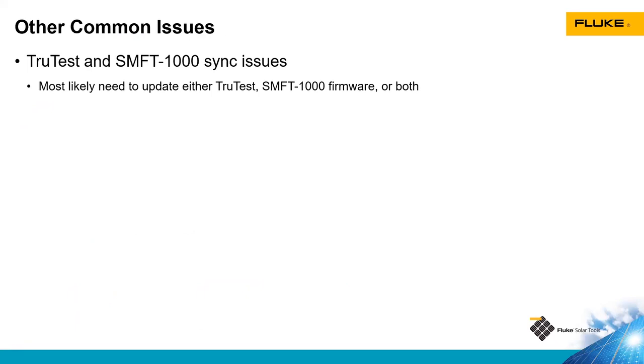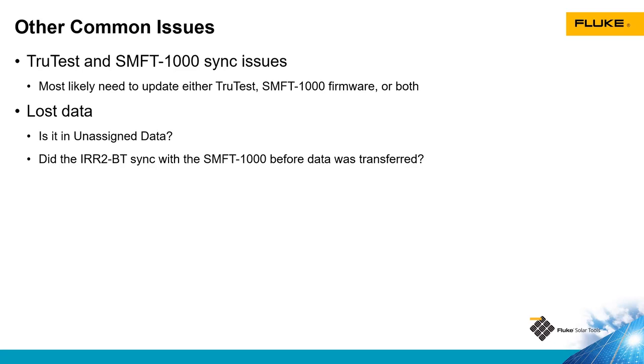Sometimes we run into sync issues with TruTest and the SMFT1000. In most cases, when that's a problem, either the TruTest software needs to be updated or the firmware on the SMFT1000 needs to be updated. Sometimes it's both. So if you're having a problem syncing data between the hardware and the software, look for updates and see if those have the most recent versions. If you downloaded some data and you don't know where it went, chances are it went in the unassigned data section. So go into that, look and see if there's data that's in there,